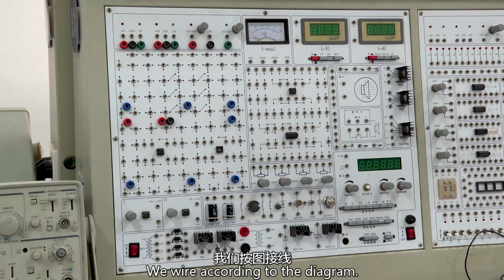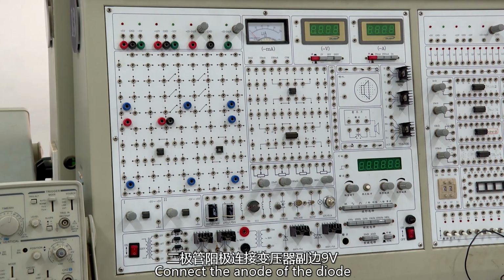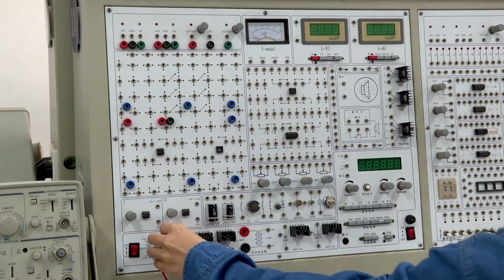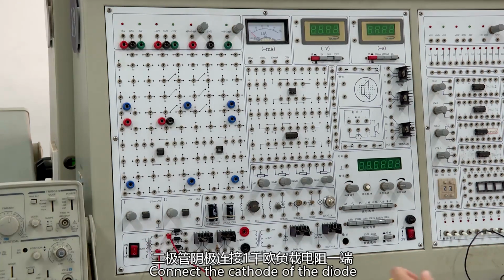We wire according to the diagram. Choose U2 as 9 volts. Connect the anode of the diode to the 9 volts on the secondary side of the transformer. Connect the cathode of the diode to one end of the 1 kilo ohm load resistor.